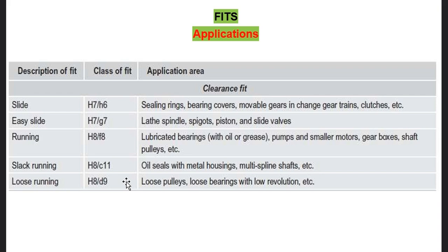So this H represents a hole with fundamental deviation H. 7 represents your international tolerance grade. There are 18 international tolerance grades. That's a different topic, but I'm just giving you the overview of that.